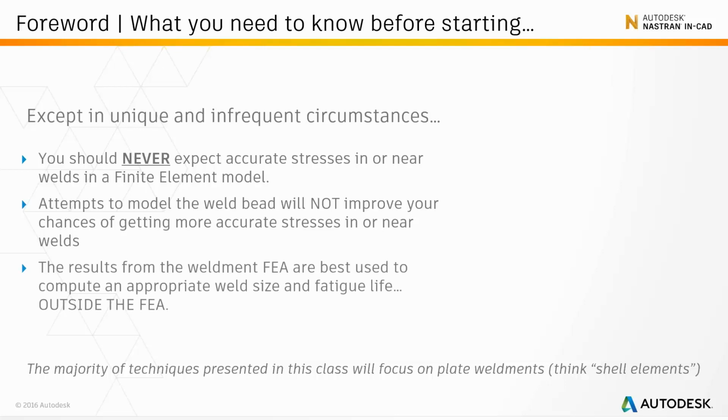And the value of FEA on welds is to help you size them outside of FEA. So it's not about actually getting your FEA tool to size the weld for you. It's about what information can I gather from my analysis results that I can then use as a means for sizing the welds.